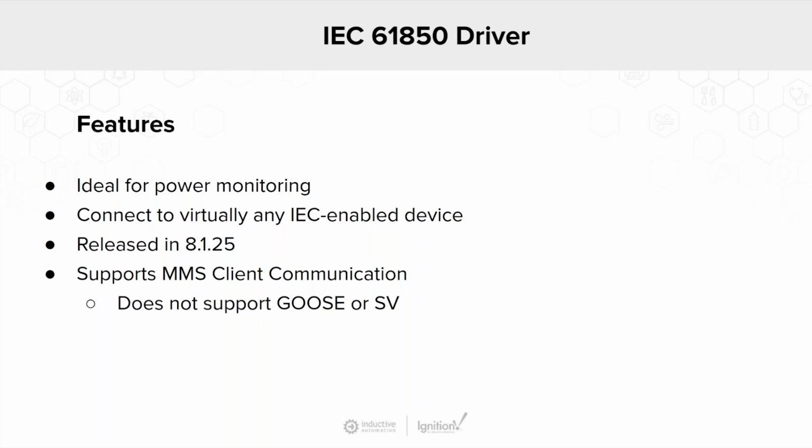Our driver only supports MMS, or manufacturing message specification. MMS communication offers meticulous control over data flow from the source to the destination through its own internal reports. This event-based communication, primarily client-server oriented, ensures efficient interaction between Ignition as the client and the server, the IED.